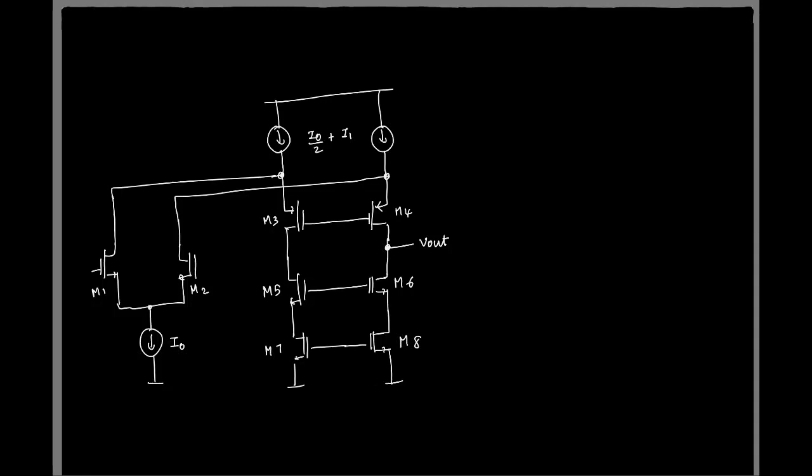So where should I make the diode connection? For the NMOS or the PMOS? NMOS, right? So from where to where do you suggest I do it? Drain of M5 or gate of M5? From here to here. Is that fine?